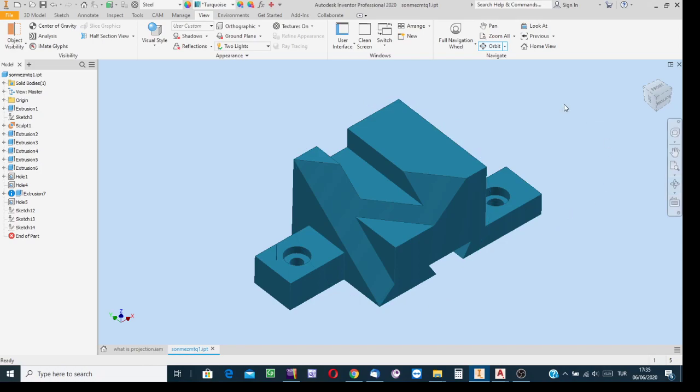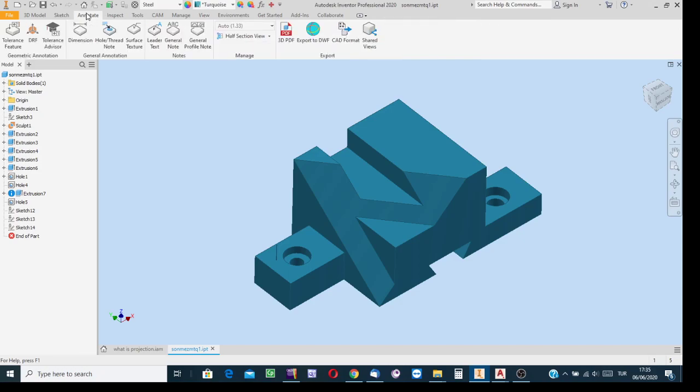And today, in such environments, it is possible to show the dimensions. Select the annotation tab, and then click on the dimension button, and then show the dimensions. For instance, indicate this one, and then show the dimension in 3D space, and then the program brings the size of that feature.